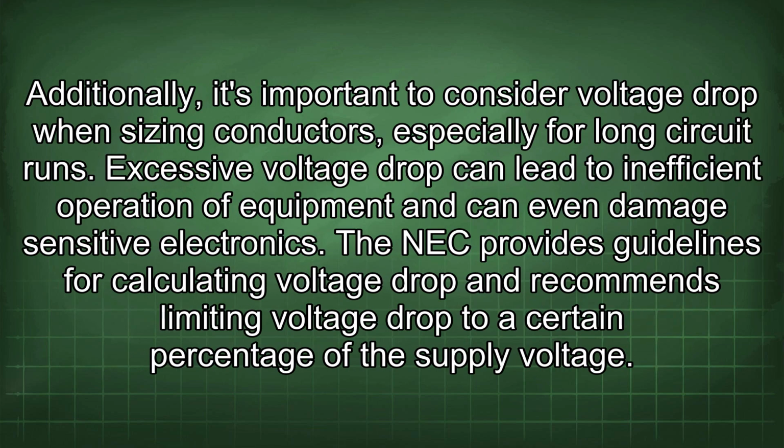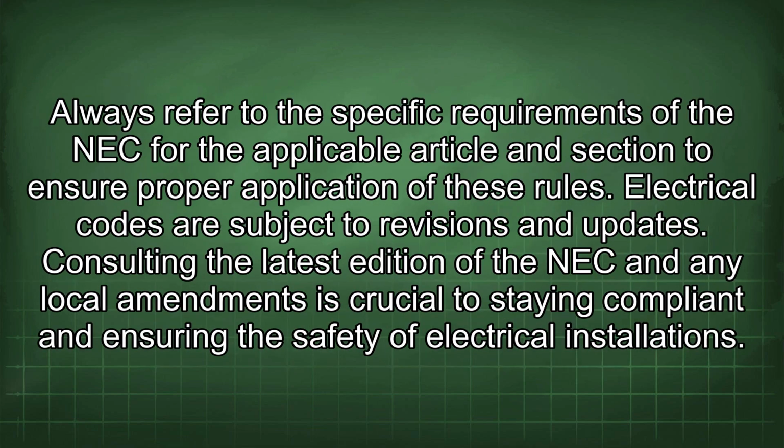Additionally, it's important to consider voltage drop when sizing conductors, especially for long circuit runs. Excessive voltage drop can lead to inefficient operation of equipment and can even damage sensitive electronics. The NEC provides guidelines for calculating voltage drop and recommends limiting voltage drop to a certain percentage of the supply voltage. Always refer to the specific requirements of the NEC for the applicable article and section to ensure proper application of these rules.